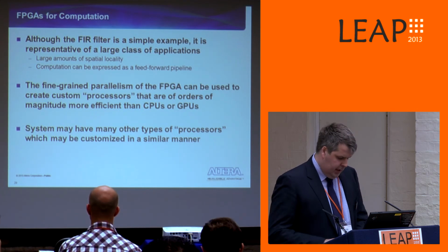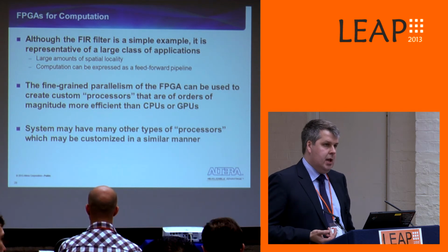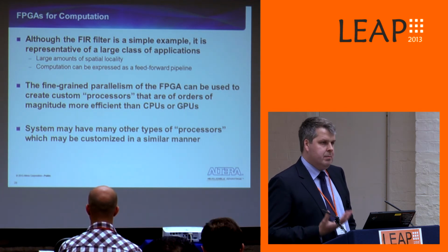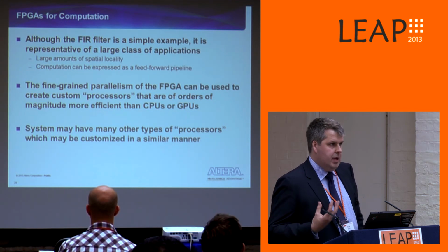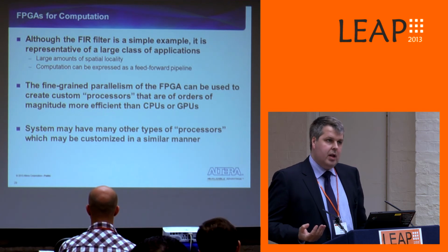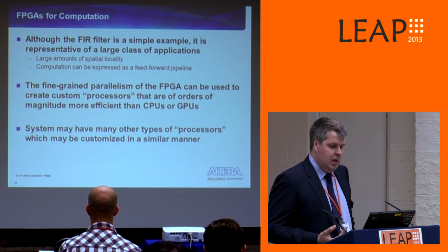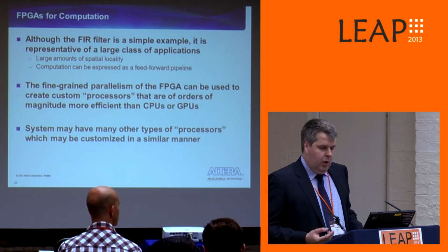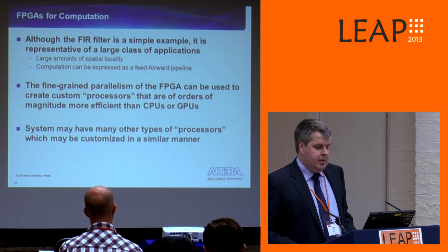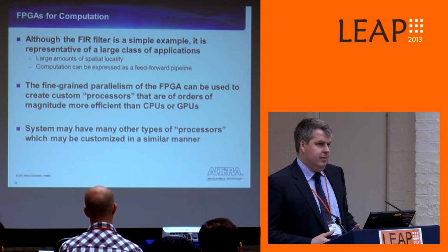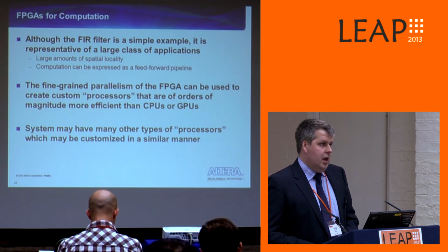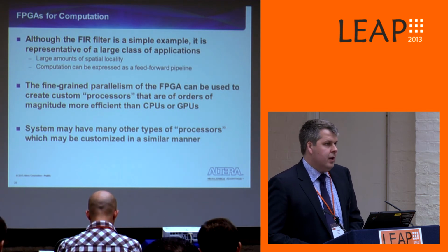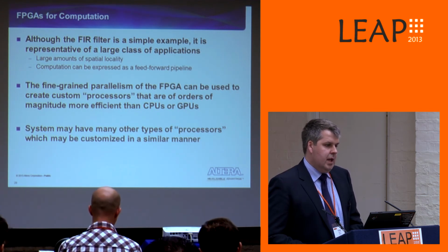The important thing, I think, is that the fine-grained parallelism of the FPGA, the ability to produce a bespoke architecture for your accelerator, and the areas of the FPGA you're not using drawing no power, gives you a very efficient implementation. And what you can see here is that there are other systems with this same sort of processor type applications that can be accelerated with an FPGA solution in a similar manner. So it's a relatively true to life application area.